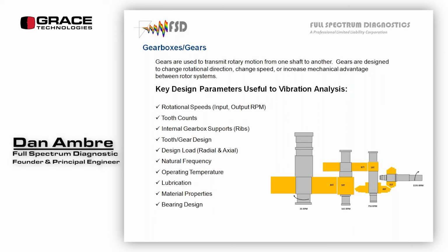But if we look on the nameplate of the gearbox, and it'll say the ratio is 0.045 to 1, that's meaningless for our applications. It's not telling us what the gear mesh frequencies are. It's not telling us what the internal shaft speeds are. It's giving us very little to trend. We can do an overall trend of the gearbox until we know what the tooth counts are, but tooth counts are required to do any good vibration analysis, any good trending, anything that's meaningful.